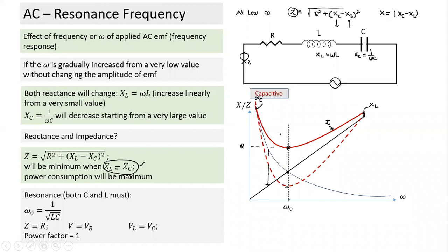And we can also understand what happens in this part, frequency less than omega naught. What is the nature of the circuit? If frequency is less than the natural frequency of resonance, the circuit will be capacitive. Why is it called capacitive here? Because for that frequency, what does this part indicate? This part again, applied frequency is less than natural frequency of the circuit, or omega is less than omega naught. It is a capacitive circuit. And the other part, this is at the state of resonance.